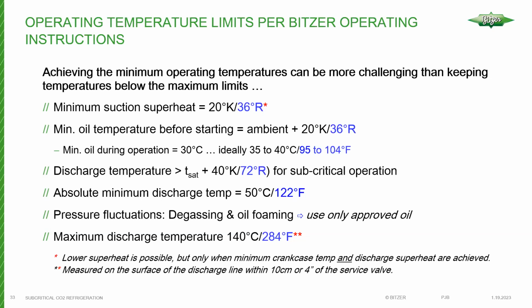And this is where we see things like foaming on startup, and we see it in HFC systems as well. It's foaming, and you've got an oil switch, whether it's optical or a differential pressure type, that can't develop pressure, or it can't see the oil. All it sees is foam. And then, of course, the timing sequence is initiated. And if we can't clear up that oil by the time the timing has expired, then of course it's going to trip on oil failure.